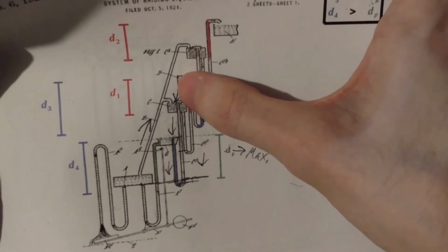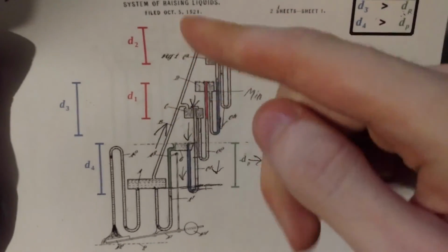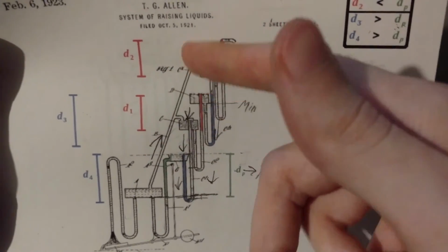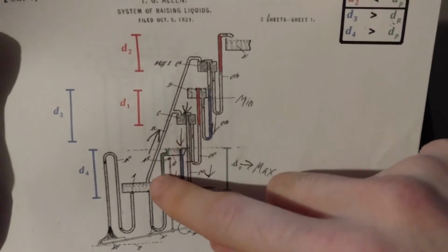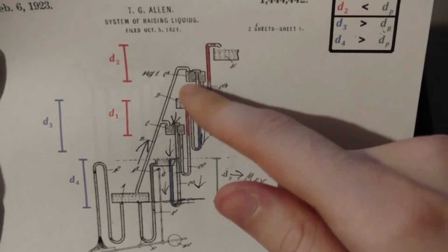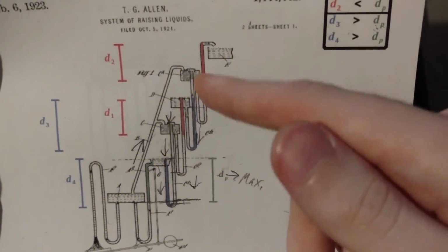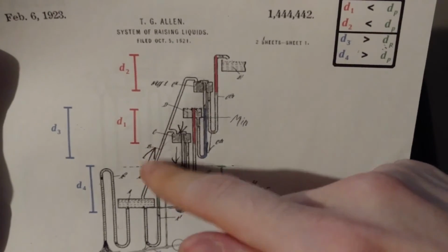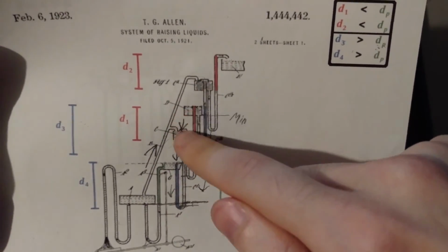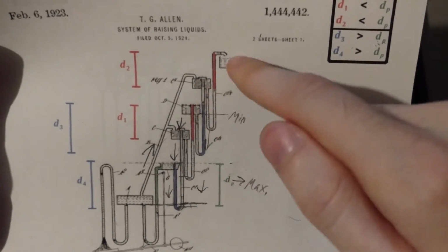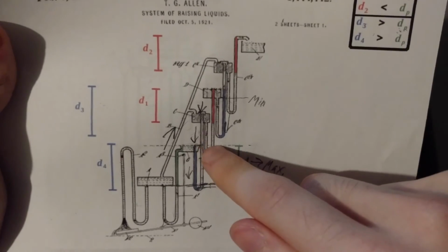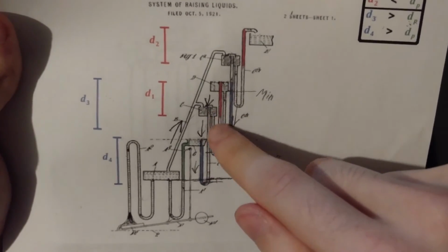Otherwise it'll bubble out and into the atmosphere, and you don't have that air pocket anymore, and you have to regenerate it somehow. So you have to open something up and let the air back in. Otherwise your system is limited, because you need a certain amount of air in here to be able to push all the water out of those tanks and into these two open tanks. So that's a problem if the air gets past those U's.